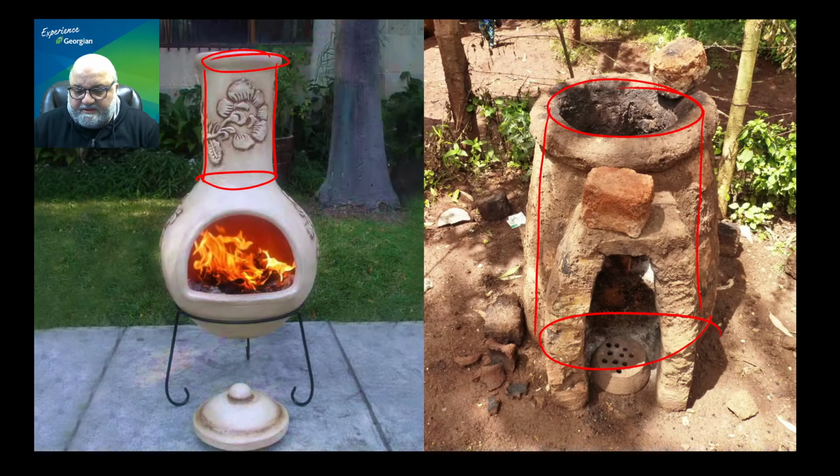But the question stands: why do we use that cylindrical shape? Why do we go to additional cost and effort and time to build that cylindrical shape? That's the question we're going to ask, and that's the question that is going to lead us to the starting point of understanding how draft is generated and, most importantly, maintained.